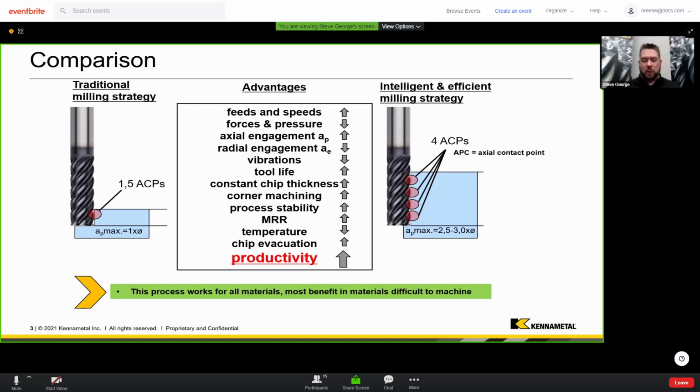The other thing that I would just say to everybody is that it's always different based on your situation. One person's finishing is another person's roughing. And what do I mean by that? Well, if I'm talking to somebody that is working in very large forgings, and they are using large diameter cutters, and they're removing a huge amount of stock, a finishing cut to them might be a similar stock removal as somebody that has produced a part by additive and is looking to clean it up and hit the finish tolerance after the additive process, right? I see more and more of that coming into play.